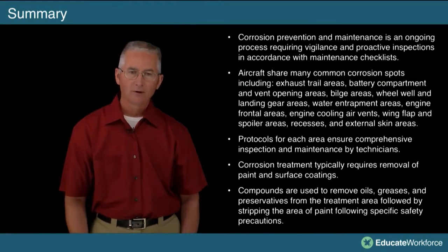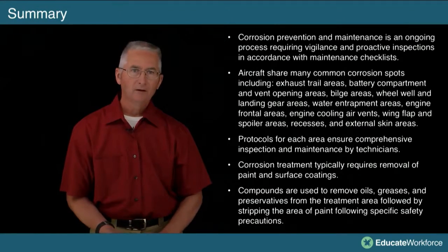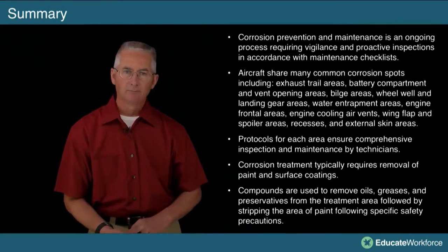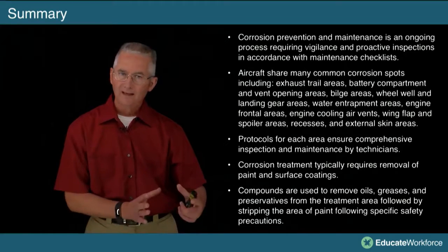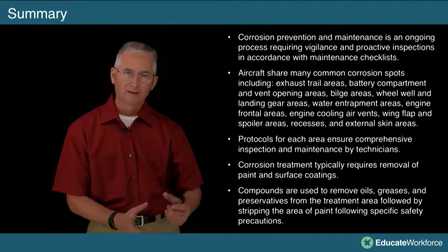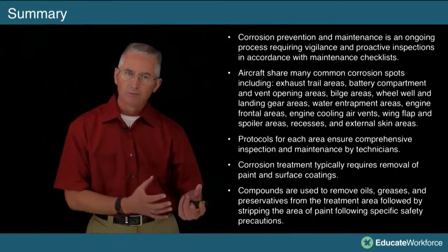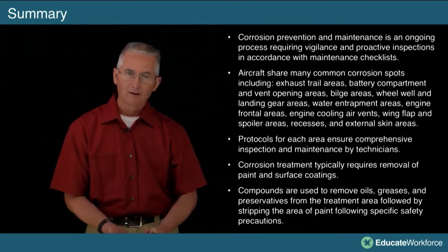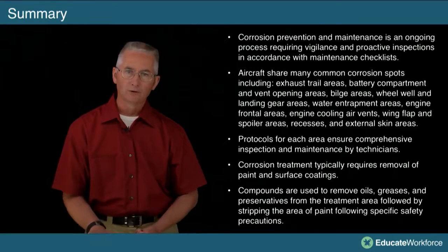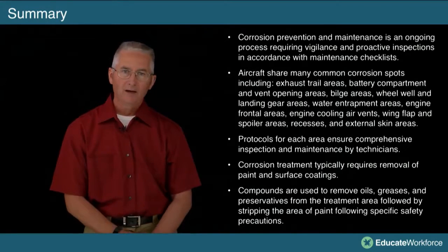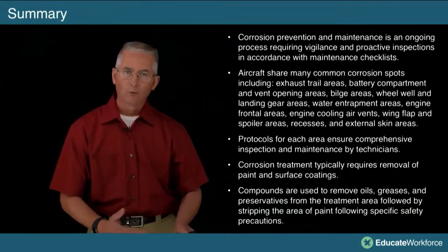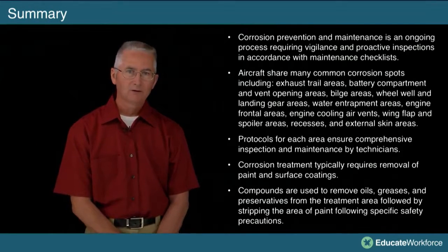The corrosion prone areas are going to be the landing gear, the flap area, the battery vents, the exhaust fumes, the bilge area, the galley. I know we didn't talk much about galley, but think about that. The food in the galley area, when it falls down onto the floor, that's going to hold moisture. Another issue that we have, sodas and pops that are going to be drank or poured and stuff like that. Think about the corrosion that they're going to cause.